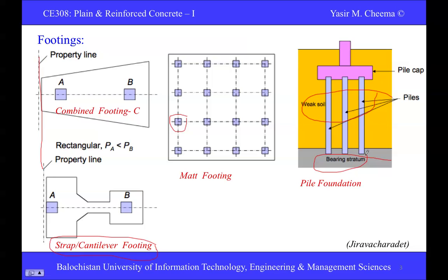There are two ways of transferring loads through piles. Either they can transfer the load by their tip, or they can transfer their loads by their shaft, or skin. There is a different debate about this, about which pile can transfer more loads. In fact, there are many types of piles, and their transfer mechanism is also variable.